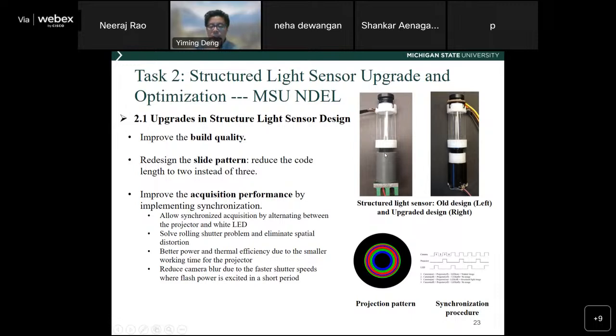It will project through an oblique angle, and the light will pass through this transparent glass tube to the wall of the pipe, get reflected, distorted by damages if there are any, and captured by a wide angle camera at the tip. Right. So this is a design which we can miniaturize the diameter of the sensor. It can fit a pipe as small as 1-inch diameter.